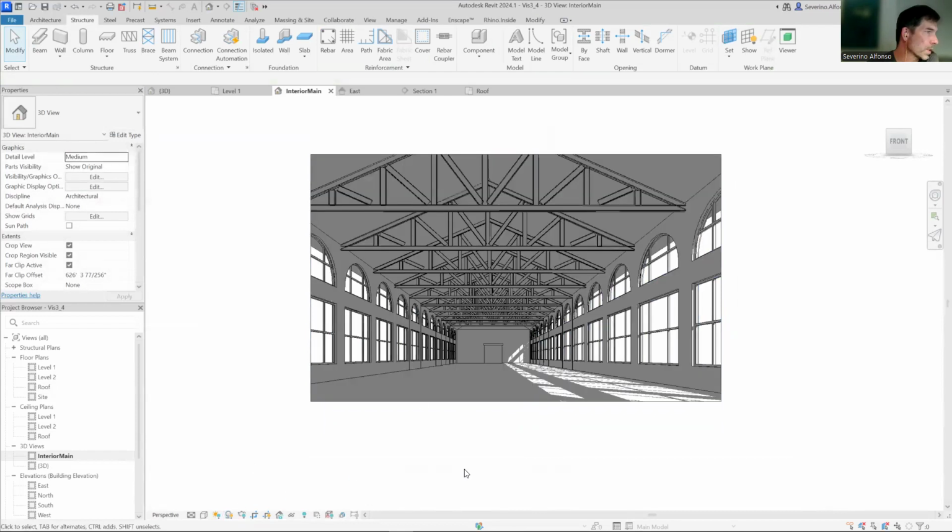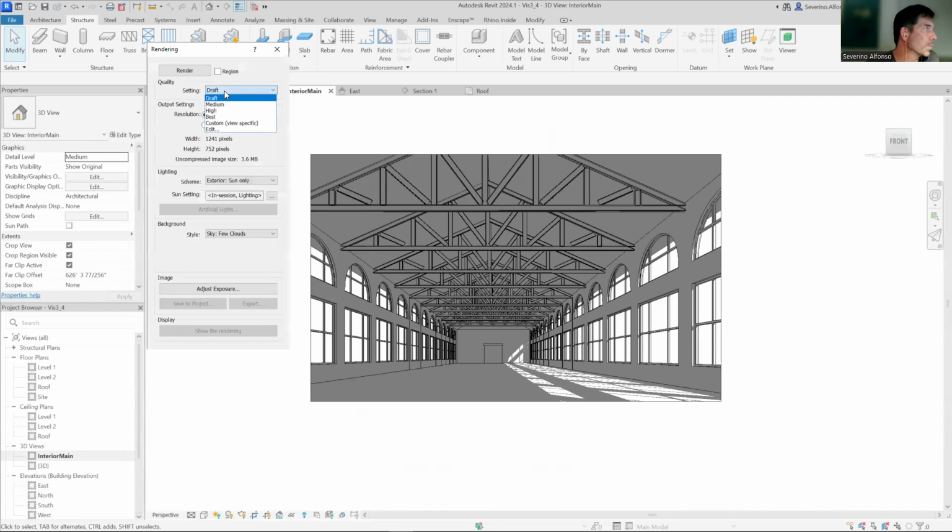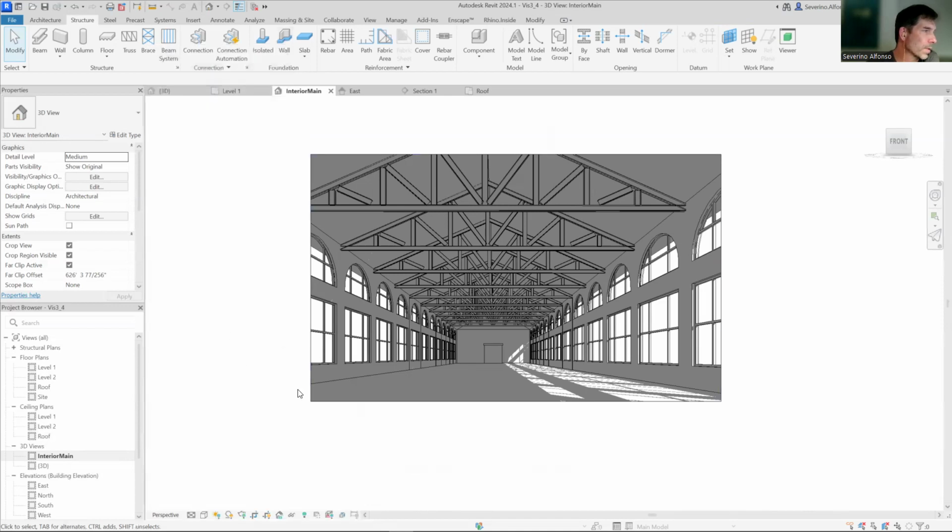So obviously we can turn on the shadows. Shadows are correct because we set the site organization. The floors can be changed already. Trusses and window panels can be changed, from the material of the glass and the mullions or carpentry. There's a bunch of things that can be done. You can also set already a tone for the renderings by setting very simple parameters from the Revit platform, which we'll see later on.